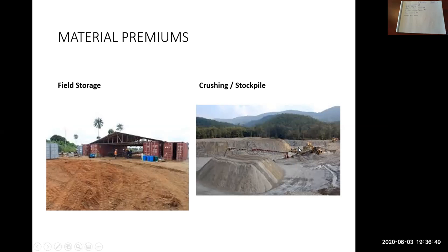The reason I bring that up is if you bring your own crushing and screening plant up, you need to have somebody that knows what they're doing to operate it. It's not just turn it on and start loading gravel into it. There's all sorts of different sizes of sieves that you need. It depends on the material that you're feeding in, what type of material you can produce.